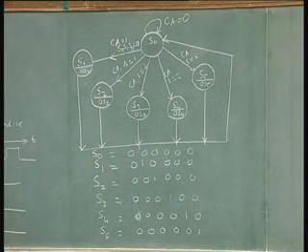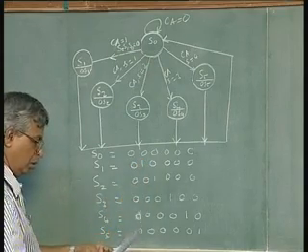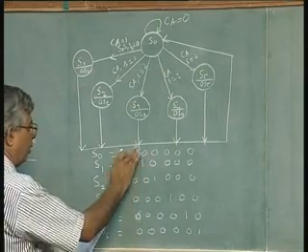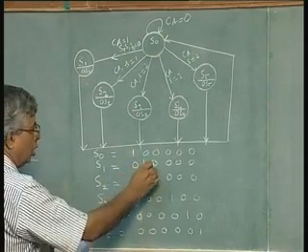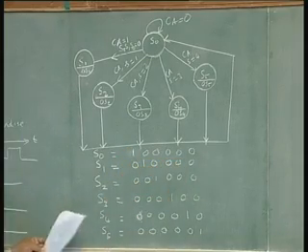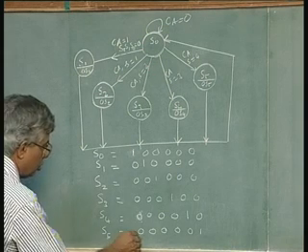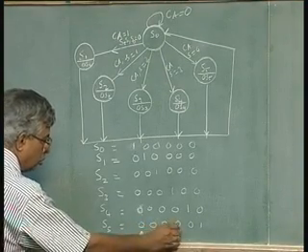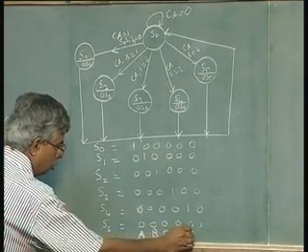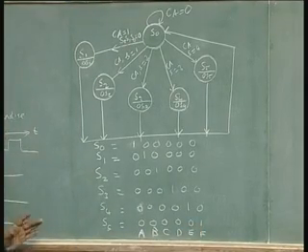So, let us say there are flip-flops, oh I am sorry, S0 should be 1. So, how many flip-flops are there? 1, 2, 3, 4, 5, 6. There are 6 flip-flops. We will call these flip-flop variables A, B, C, D, E, F. So, I am going to use 6 flip-flops for 6 states.